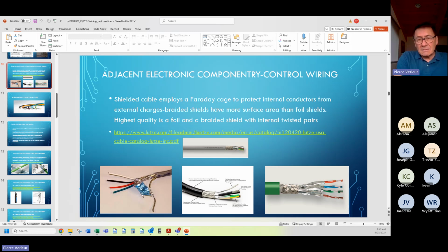This, you get credit for that effort, but you don't get full credit, and you're going to get some problems that you would not have using this technology. I recommend this on the power leads as well. It makes sense to shield your power leads because now you're suppressing the noise at the source. You're not waiting for it to get out all over hell's half acre and affect all the conductors that you then individually protect. Why not protect both?